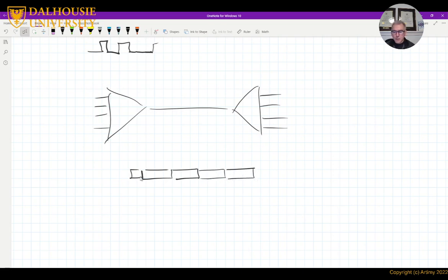And then let's say the sync bit or the control bit. So each one of these, let's assume it's a 10 bit. The number itself is not important. The first pair sends 10 bits, the second pair sends 10 bits, but the third and fourth pairs don't have 10 bits, they have only 6. So what happens? We don't have enough bits to fill the time slot.